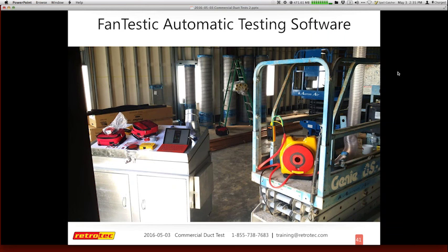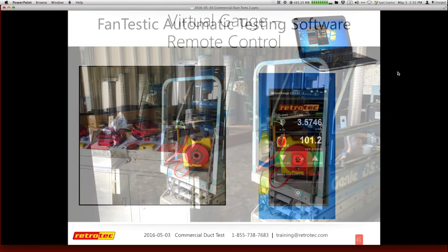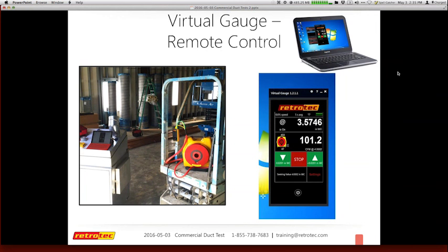I'm going to go through the gauge and how to change your results, so you can be familiar with it. Some people may have the gauge already and are familiar with it, but if not, you can understand the process and how to go from getting my results in CFM, which we saw earlier. One of the SMACNA results is CFM per 100 square feet of duct area. So it's a matter of tapping channel B and going from CFM to CFM per 100 square feet. There's a variety of options, so I'll go through them so it may be familiar when you actually use the gauges.